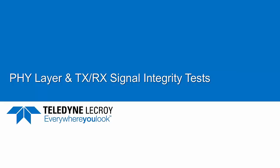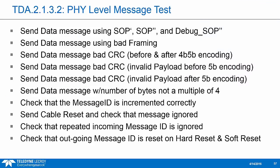PD uses very low speed, low impedance signaling, but there are PHY layer specific tests. CRC checking is done at the PHY layer before passing messages up to the protocol layer. In test 2.132, we unload a barrage of error conditions on the UUT and make sure he can handle them. In general, if you get a bad PD message with a bad CRC, you're supposed to ignore it. We also check the proper message ID handling and resetting.